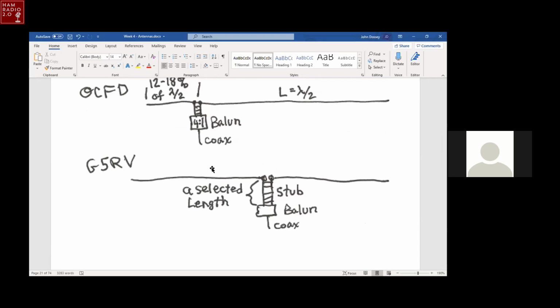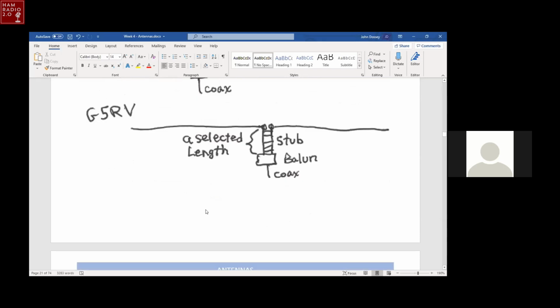So it would still be a multi-band antenna, and that would make it work best on 20 meters, which is a good band to have a good antenna on. So you're saying that you use a quarter wavelength for this length of the stub and ladder line? It's approximately, yes. Okay, so it's not real critical then. And so that will match it for multiple bands.